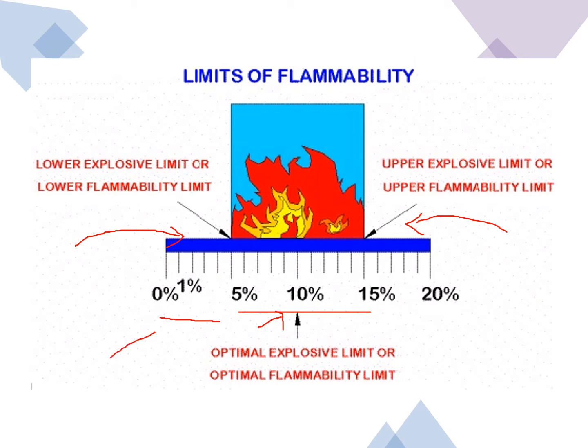So the vapor limit is less, but oxygen is higher, because the vapor density is less. But here you can see 15 to 20%. Here the vapor limit is higher, that's why we call it a higher limit, right? So oxygen will be less here, but the vapor concentration is higher, so that's why an explosion does not happen.